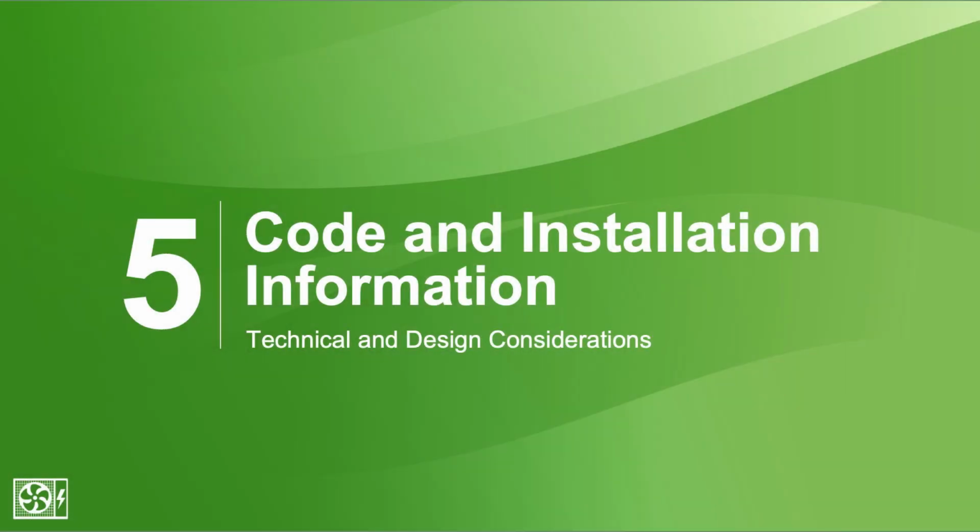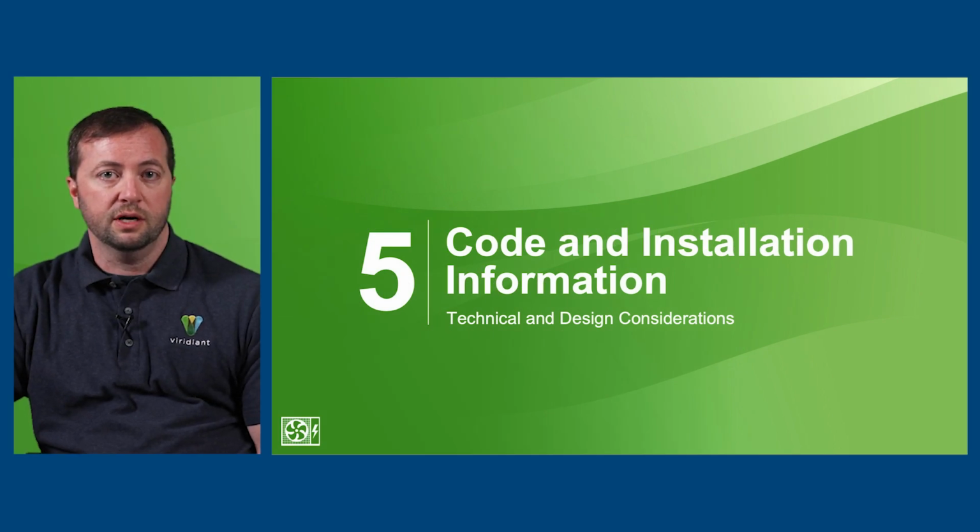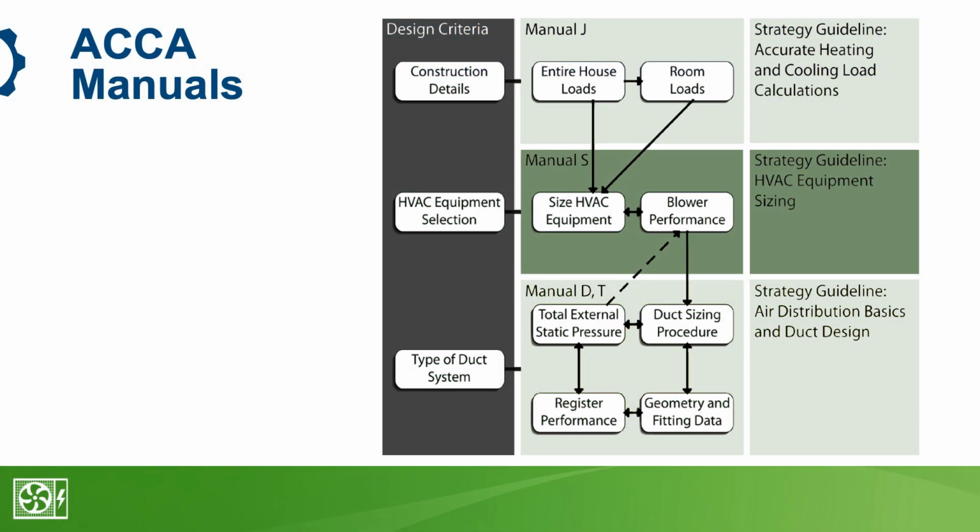Code requires that all HVAC systems, including heat pumps, are designed and installed in accordance with industry standards for calculating the sizing, equipment choice, and duct layout. Here we see a diagram showing the 4 key manuals from ACCA, the Air Conditioning Contractors of America. The manuals are books that software packages are then built off of that get into all of the engineering details